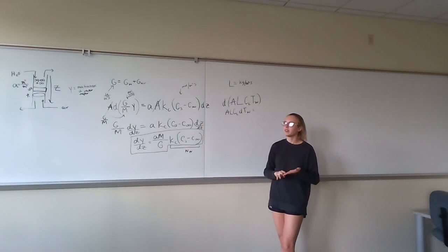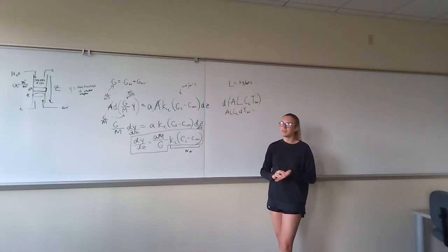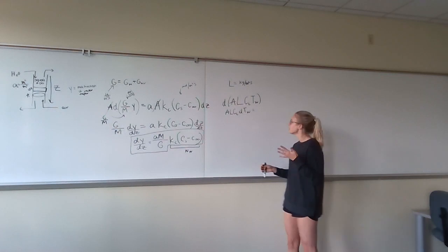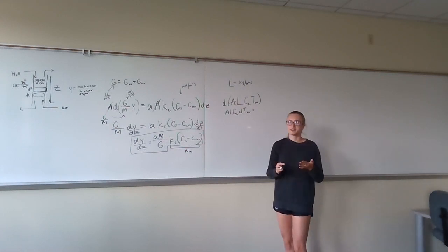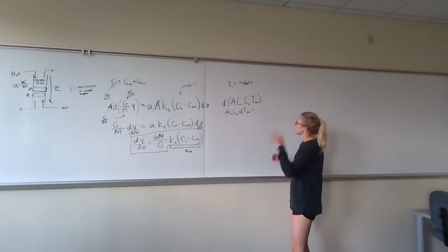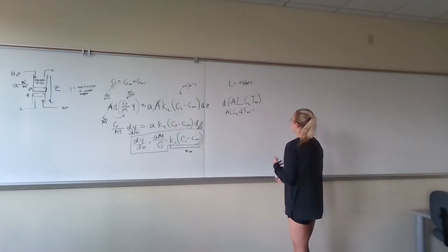So we know that the two components for the change in enthalpy of this liquid water will be the heat of vaporization, because water is evaporating from the liquid phase into the vapor phase, and then also the heat transfer of the water to the gas phase, since the water is hotter in this situation.